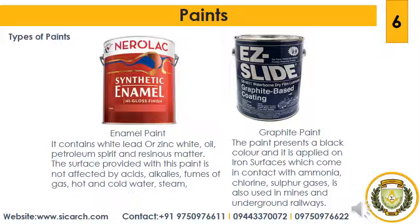In order to improve the appearance, it is desirable to apply a coat of titanium white in pale linseed oil before the coat of enamel paint. Graphite paint. The paint presents a black color and it is applied on iron surfaces which come in contact with ammonia, chlorine, sulfur gases. It is also used in mines and underground railways.